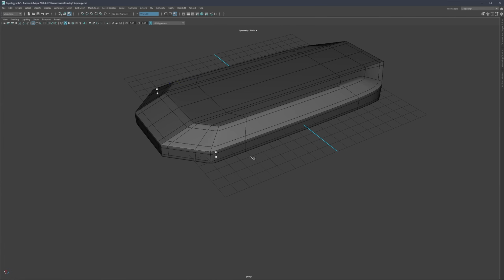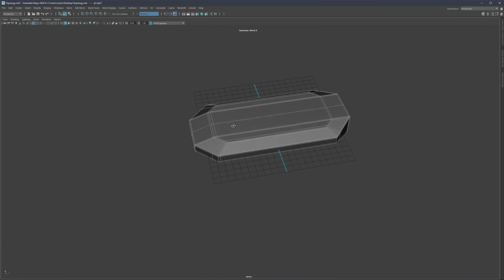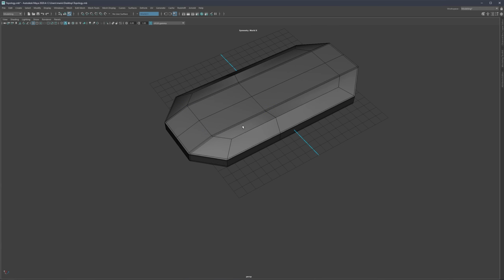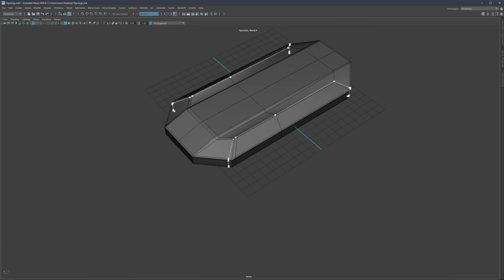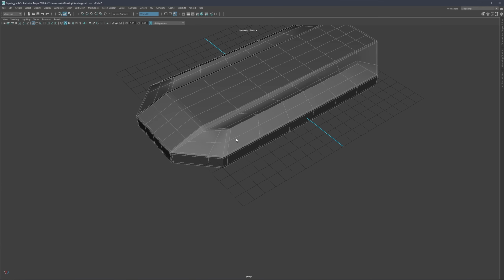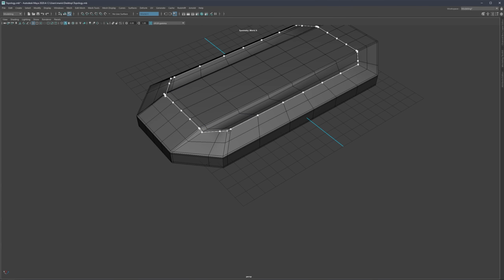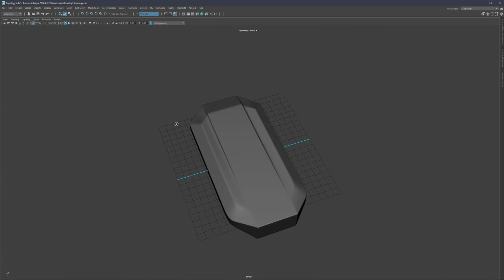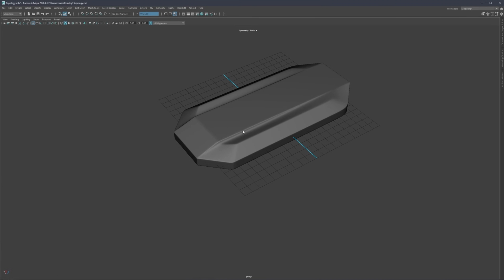I mean, this is at least the basic part of it all, because let's say again I would like to do some more adjustments here, and maybe I want to push this even more down, tighten this more with the support loops, and get something like this. So there we go. From very simple, just by following the simple rule, adding supports and making sure that we have a proper redirection, we can get the basic shapes pretty fast.